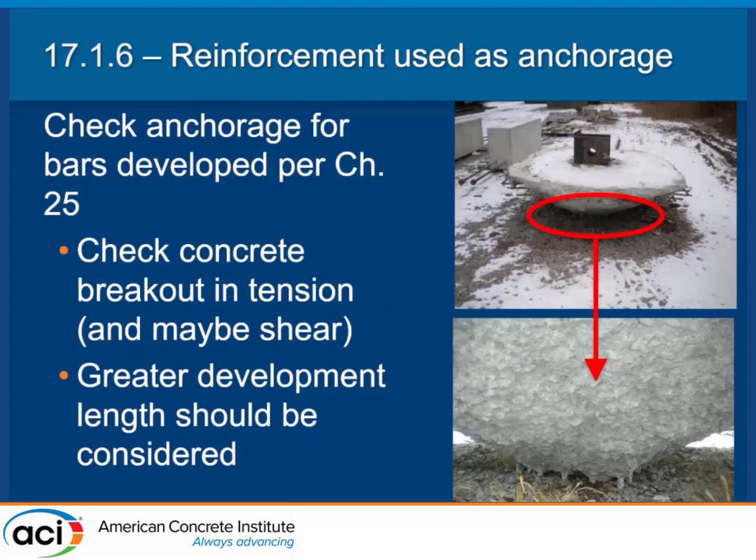And here's a case where I was saying, you can use reinforcing steel welded to the bottom of a plate if you want to, right? You don't have to use all these other anchors, but when you do, here's a case of a radio tower. We have big guy wires that came down and they were anchored into just big hunks of concrete. It's a fairly substantial, big hunk.